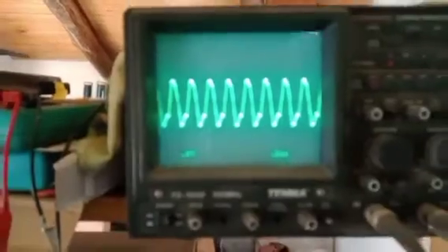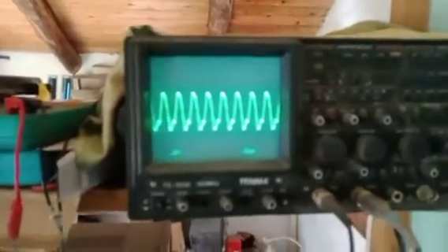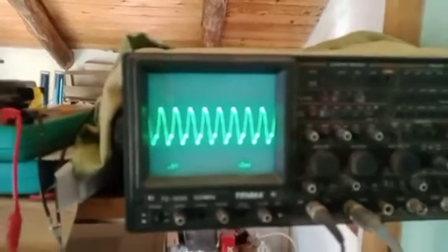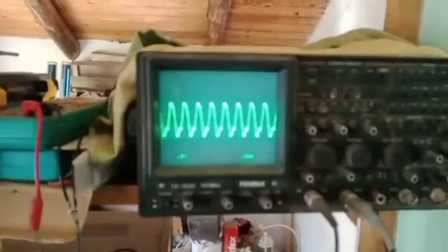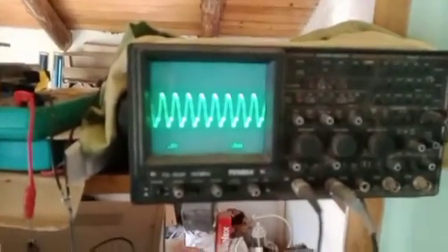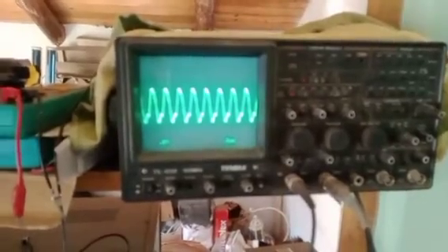It is not properly blocked, and I think at this moment this is not due to the reverse recovery time, but the internal capacitance of the diode. For this reason, the small diodes perform much better than the big ones.